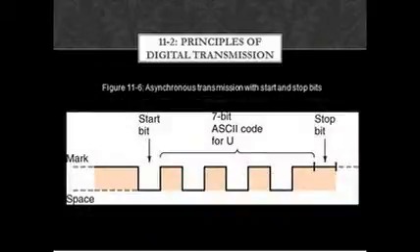In this diagram, the start bit has become the same direction as all other bits in the data word. The transition from mark to space indicates the beginning of the word and allows the receiving circuits to prepare themselves for the reception of the remainder of the bits.